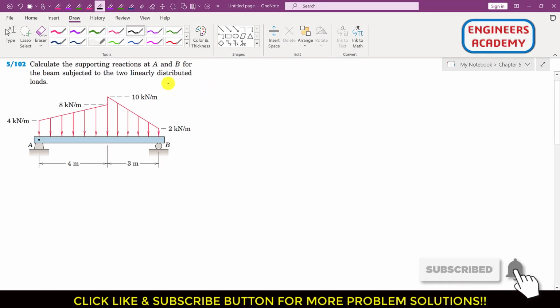Let's solve another problem from the distributed loads topic. In this problem we are required to calculate the supporting reactions at A and B for the beam subjected to the two linearly distributed loads. So we have this beam, and it is subjected to these two linearly distributed loads. What we will do is replace these two distributed loads by only one concentrated load.